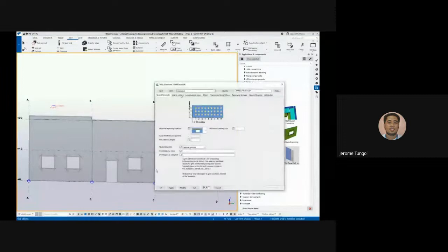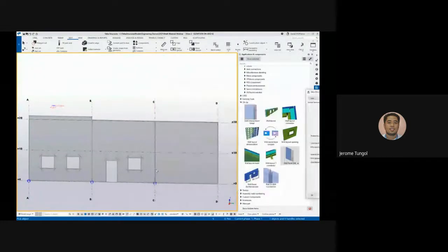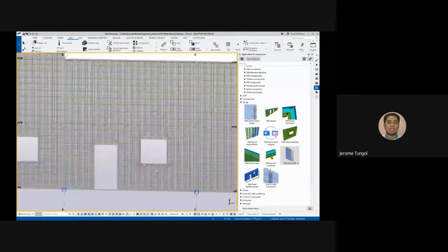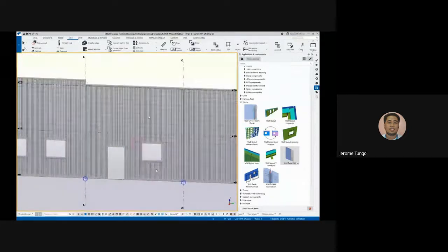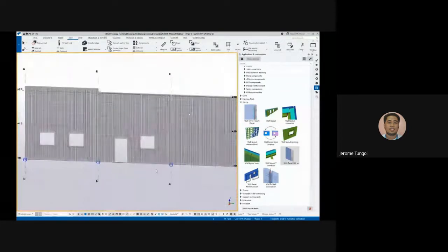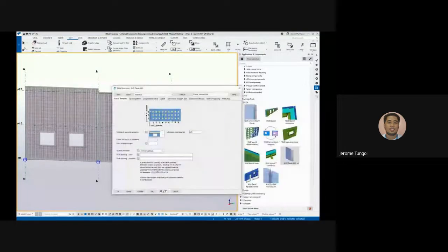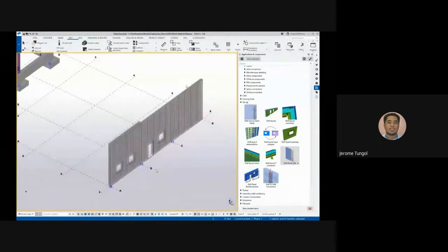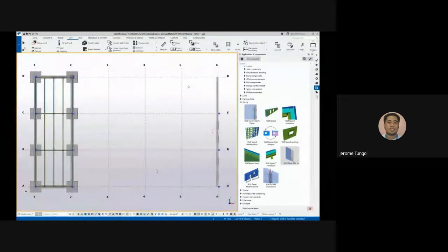And then for the main bars of the walls, we have a wall panel wherein again you just input all the data based on the design, and then just click the wall and the reinforcement will be placed in the right position. And just like that, you complete a wall model with complete reinforcement. So that's for our concrete part.